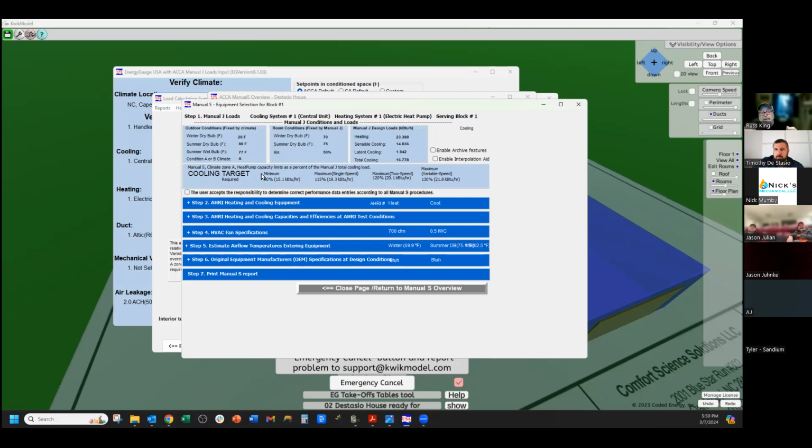The new normative section has been published, and it is reviewable right now. I think if you go to the ACCA website, there's a link to it there. That's the code language part of Manual S. The other part is called the user's guide, and that's being developed right now and should come out pretty soon. The thing about the new Manual S is they spend a lot more time on heat pumps. Instead of 2 options for heat pumps, there are now 9, and how you size them, whether you want the heat pump to meet all of the heating load or not, whether you want to avoid supplementary electric resistance strip heating and stuff like that.